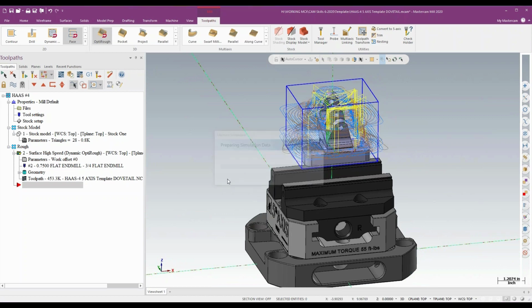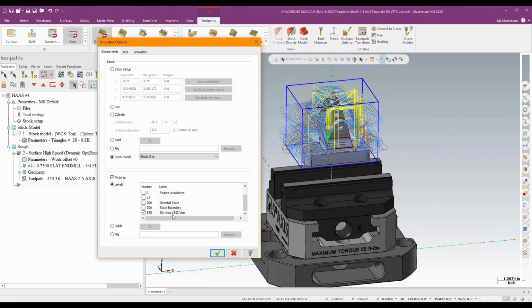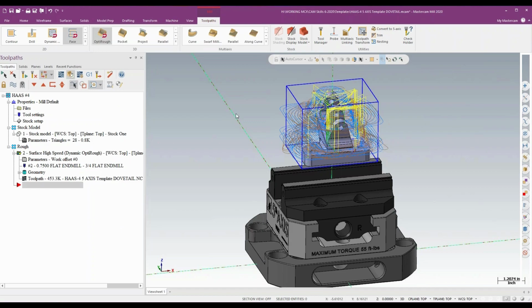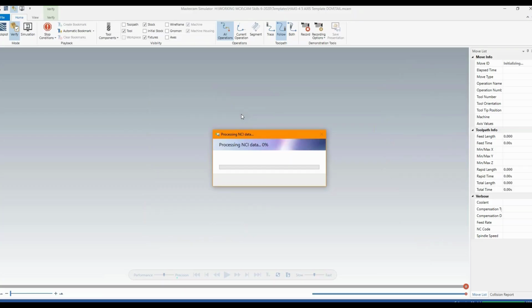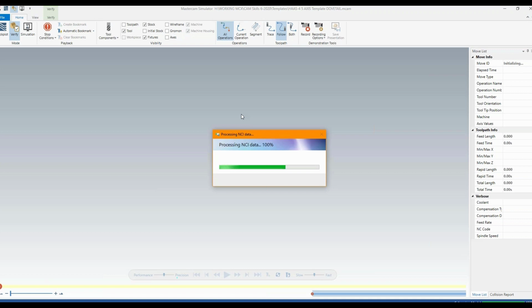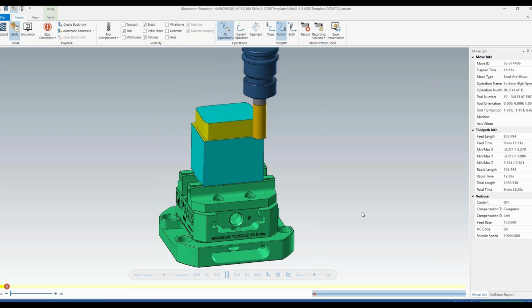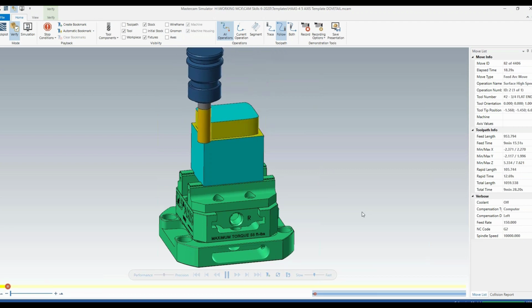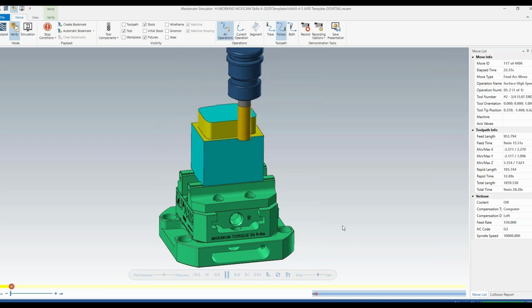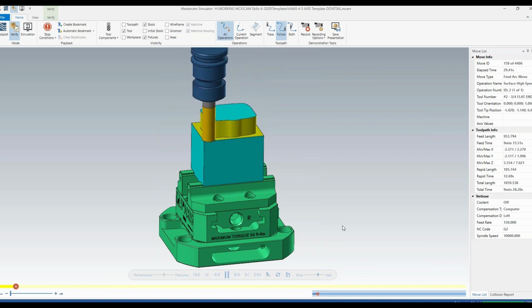And if I have this set just to make sure that I'm using that stock model, there's my fixture. I can immediately jump into verify, and I'm, again, just further along that curve faster. I'm already into verify. I'm already evaluating and making adjustments to the toolpath, things I like, things I don't like. My feeds and speeds are there. The step over is what I expect it to be. All of that stuff that I sometimes might forget, those little tiny details that seem to slow down your momentum when you're programming, I can have that already there for me. And it just makes it that much quicker.